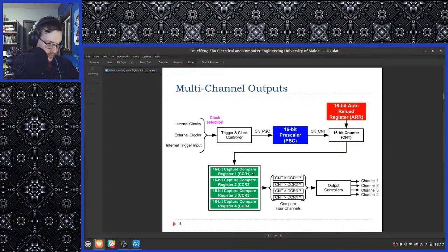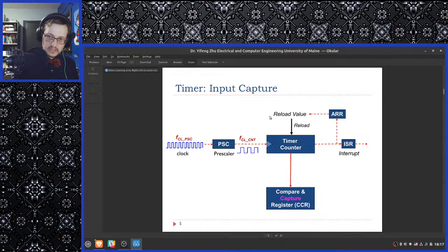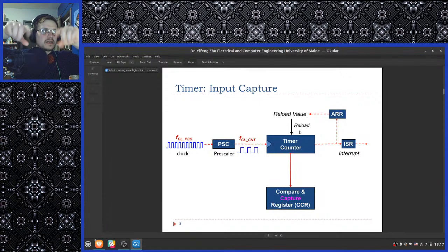Wouldn't incrementing the counter require arithmetic from the ALU? And if this is happening in every clock cycle, wouldn't it take a lot of processing power away from the actual programs? Excellent question, Connor. Thank you very much for asking that question. No, because this isn't being done by the CPU. This is an external peripheral. So the register that's being held here is internal to this. Think of the timer as being a separate chip, right?